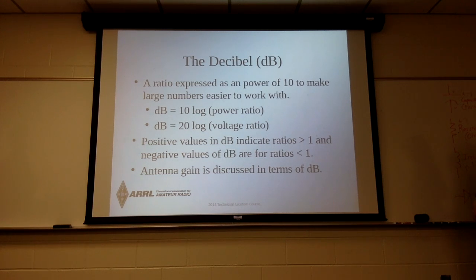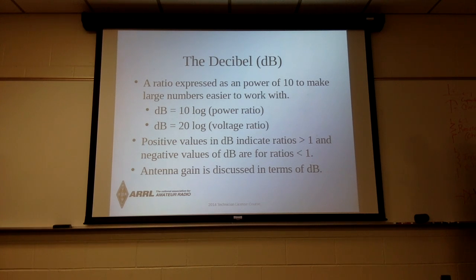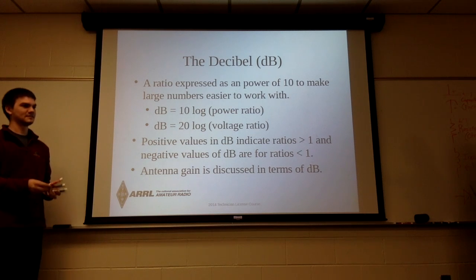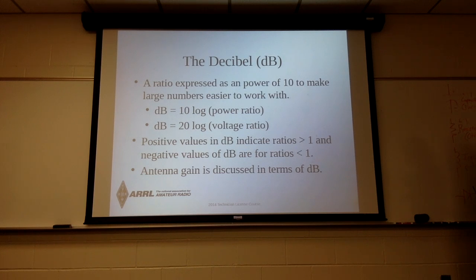Yes? Can you talk a little bit about circular polarization? Not just polarization in the context of, let's say, simple Yagi antennas. I would say the easiest take-home point here is if I have a Yagi that's horizontal and someone else has a Yagi that's vertical, it's not going to be near as effective as if both of them are horizontal or both are vertical. They need to be polarized the same.